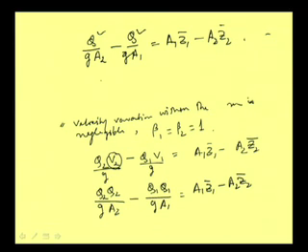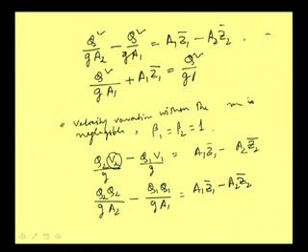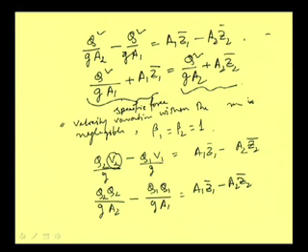If we bring one term to one side, then we can write that Q square by g A1 plus A1 Z1 bar, taking this to the other side and then bringing that to this side, we can write Q square by g A2 plus A2 Z2 bar. These two terms are equal, and this term itself is called specific force. So, from deriving the momentum equation, we have that the specific force at this point and the specific force at the second point are equal.